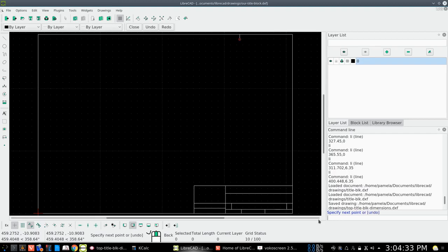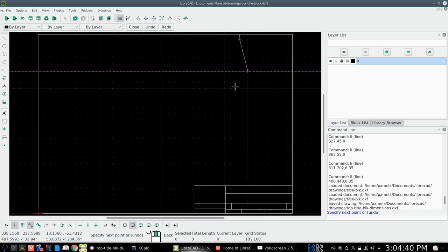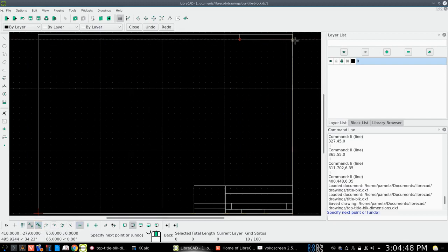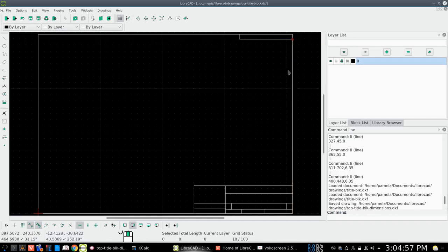You see it popped up here? Now, we can just go over here, but we have to set our horizontal snap first. So let's take free snap off. Let's snap on entity, and let's go horizontal snap, and right there. Let's right click, get off of that, and right click again.